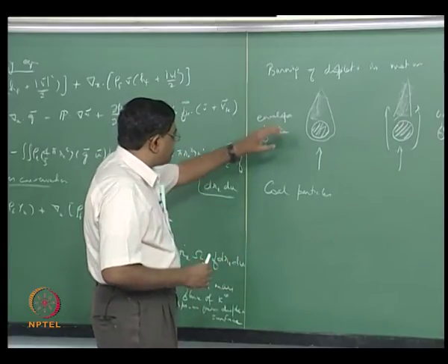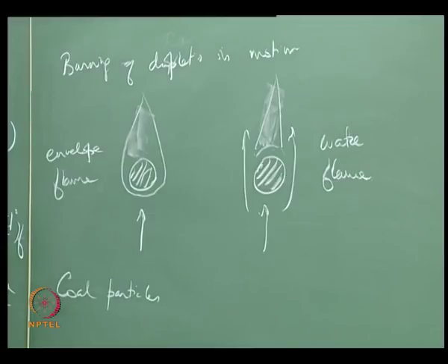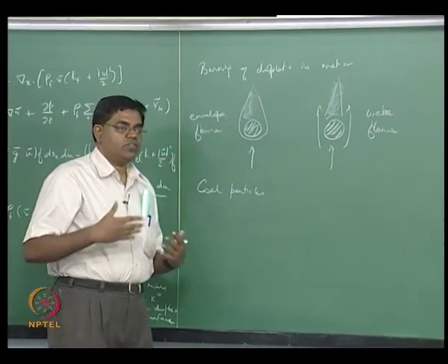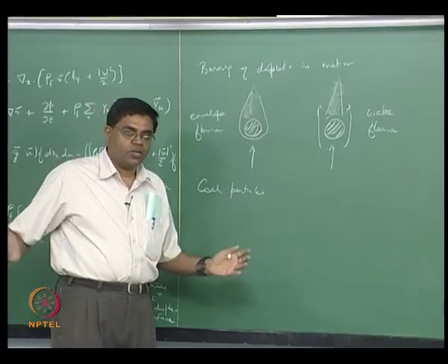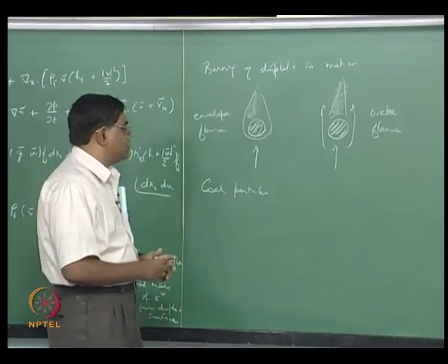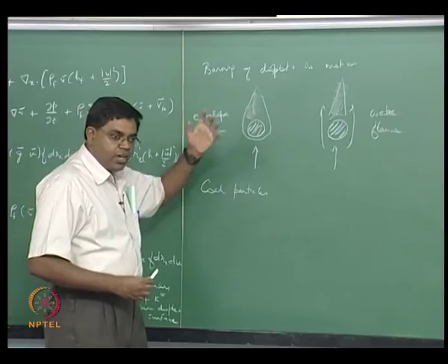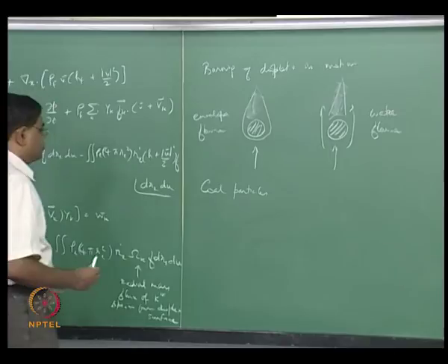But if you still look at liquids, the more volatile ones can actually volatilize from the core and bubble through the less volatile ones and can cause what's called a secondary atomization. That means it shatters the less volatile ones into smaller droplets, which form from a single parent droplet. So the single parent droplet itself was obtained by atomization, but then you have a secondary atomization because of this. So such things are possible.